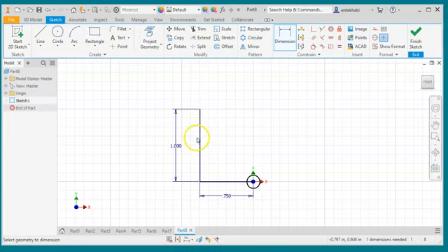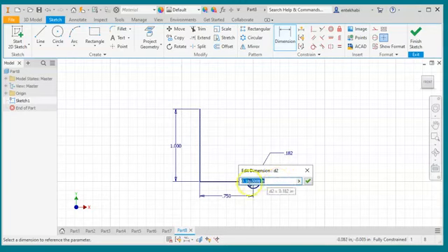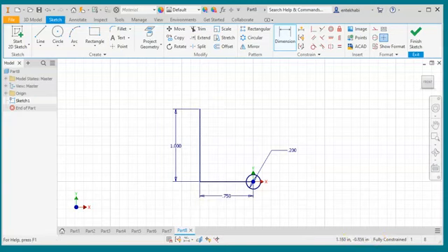Even if it's not 1, you can always create a different size, but when you type 1, it's going to be the same. This doesn't have to be the same as your height, because height is part of the settings that we will be adding within the coil tool. So this diameter is given 0.2, and that's all we need for the sketch. It is fully constrained. Finish sketch.